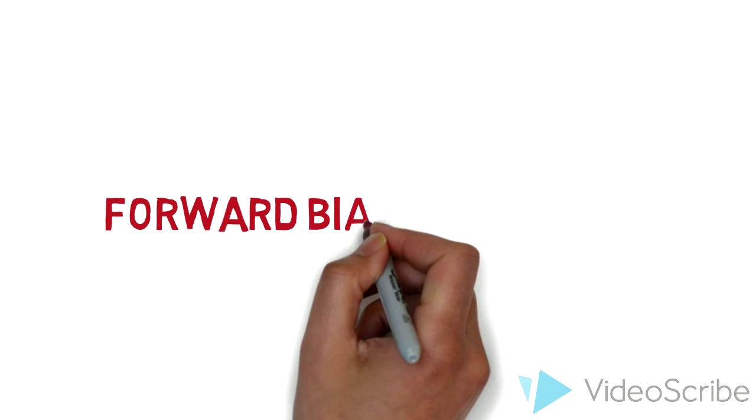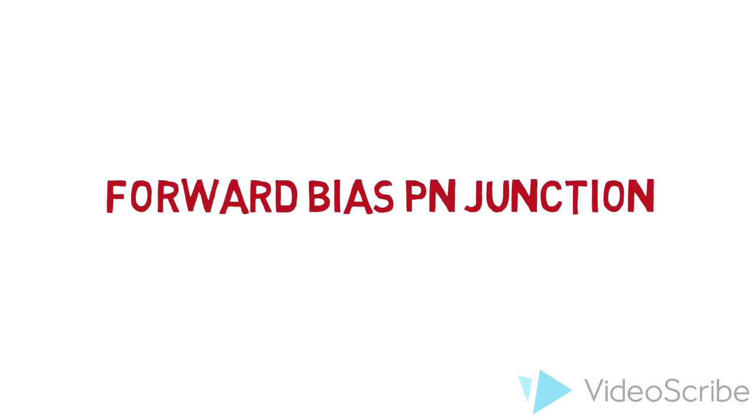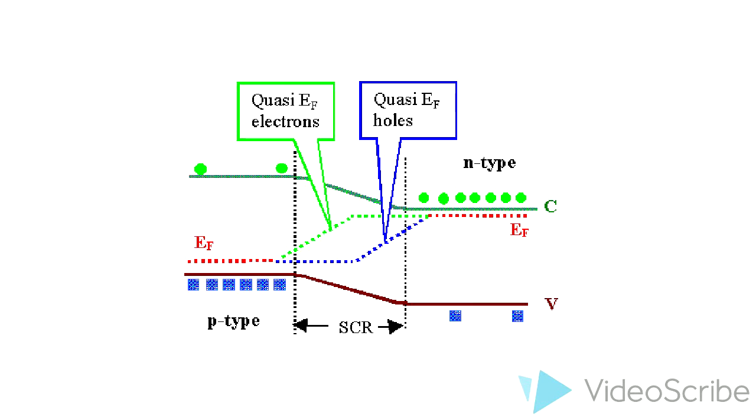Meanwhile, when a positive bias is applied to the P side, as in the current drawing, the potential difference is lowered between the two sides. This is demonstrated by the lesser slope in the Fermi levels of each side, and they are no longer equal. They are called quasi-Fermi levels. This leads to hole diffusion into the N side.